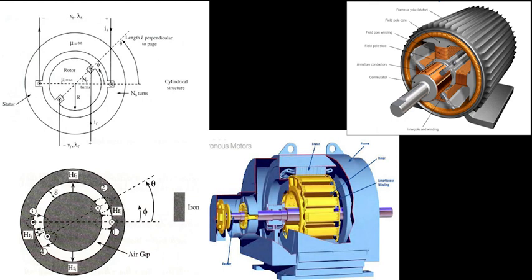This machine takes advantage of electromagnets, and sometimes permanent magnets, to manipulate magnetic fields in order to induce a current in the stator by rotating the rotor, or produce rotational motion in the rotor by running a current through the stator. Because of this, rotational systems are integral to the conversion of electricity and mechanical energy.